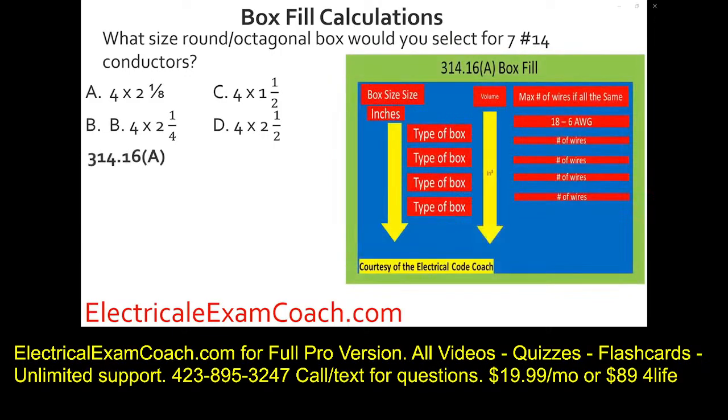We're going to head to table 314.16a. We're going to start here on the right-hand side and we're going to find our gauge wire. Then we're going to come down and find a box that fits it and be sure when we cross over that we stay in the right category of box, and we're going to select C.